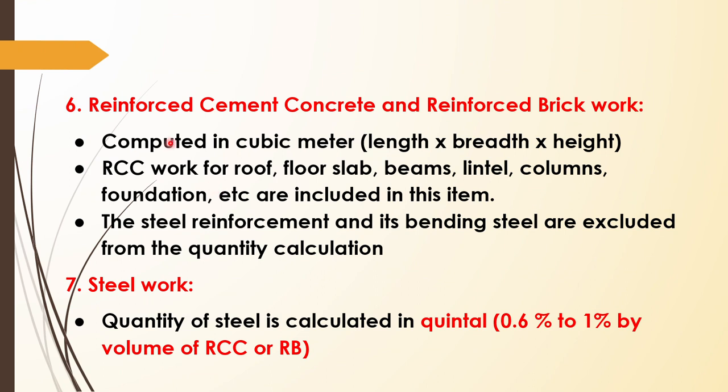Now the next work is reinforced cement concrete and reinforced brick work. In most of the cases we'll use reinforced cement concrete only. In some cases we'll use reinforced brick work. So these are nothing but we are providing steel members inside concrete for increasing the stability and for bearing the tension. Okay. Now that RCC work is calculated in terms of volume, that is cubic meter, length into breadth into height is taken.